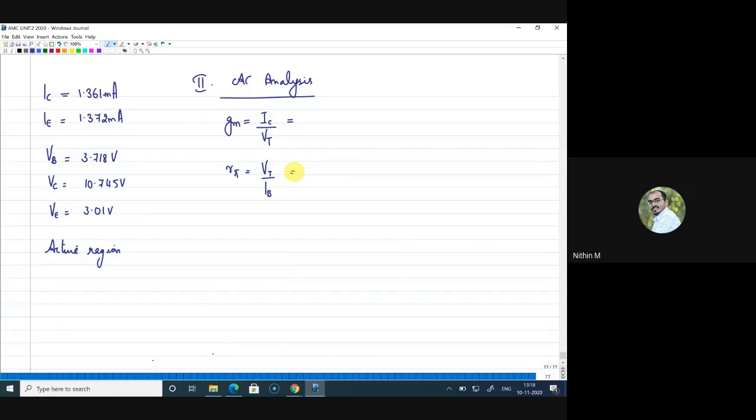Thank you, Nishant. Now let me check with Nitin. Nitin, are you there? Nitin, can you tell me what is the gm value? One more thing I'll say here, gm is actually equal to alpha by re, or it can be taken approximately equal to 1 by re. Can you tell me what is gm? Yes, sir, one minute.